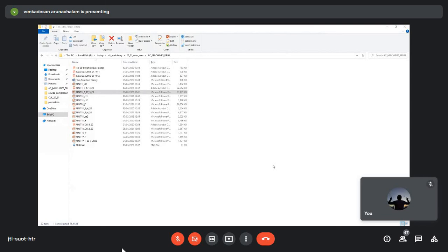So root 3 by 2 times phi m whole square plus, so minus already it has become plus. In order to add vectorially, you have changed the direction. So root 3 by 2 times of phi m whole square plus root 3 by 2 times into root 3 by 2 times phi m squared into cos of angle between these two.